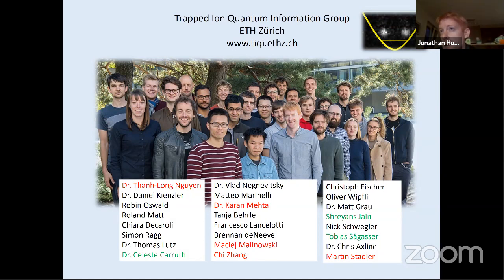I think it very much depends on the speeds that you do your gates at. So in our approach, we use red lasers, right? So we have a milliwatt coming out of the coupler at the moment. We have a rather large spot size, 3.5 times 6 microns. So you can imagine we're not using all that power super efficiently in terms of the intensity we get. But of course, scaling to many channels, I think we haven't done a proper evaluation of the dissipation that's happening in those devices. And how does the light escape? I mean, it goes into some of the materials, but we don't know what the absorption rate is at a certain level. So I think it's relatively hard to quantify at the moment, but we also haven't really tried.